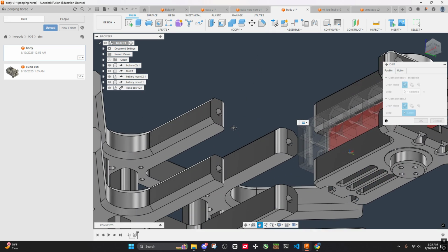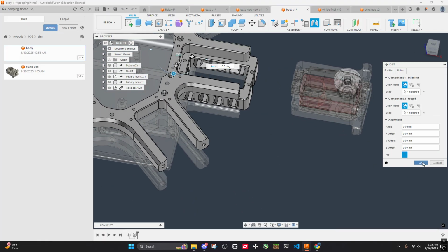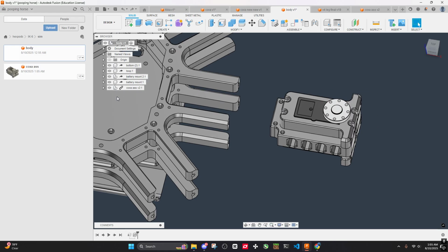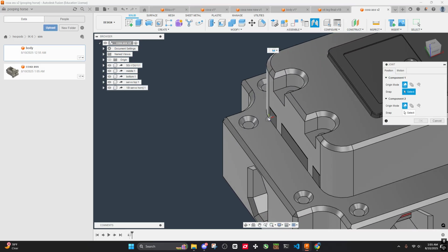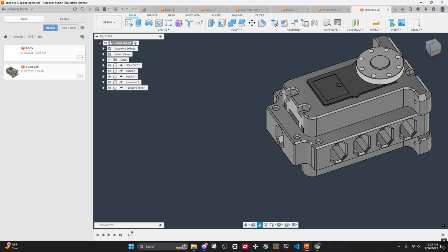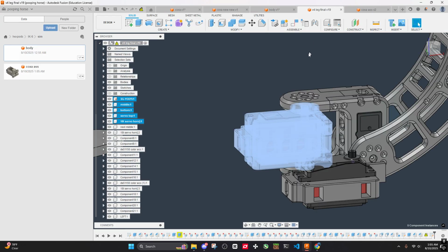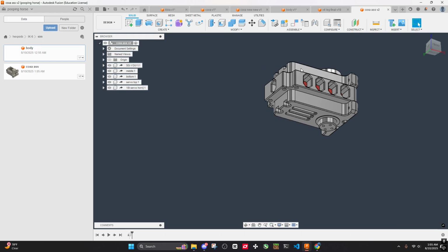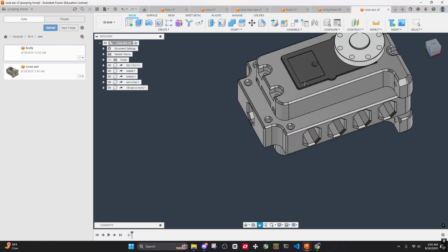If I do a joint, would it work? If it doesn't, then I can just do a move. It didn't work because you didn't joint all the parts together in the assembly file. You can do that, and then it'll work. I need you to joint everything together. The joint type is supposed to be rigid joint. Yes, that's what I have here, but I just don't know how to do it. If you do it once in the Coxa assembly file, you don't have to do it six times. Okay.